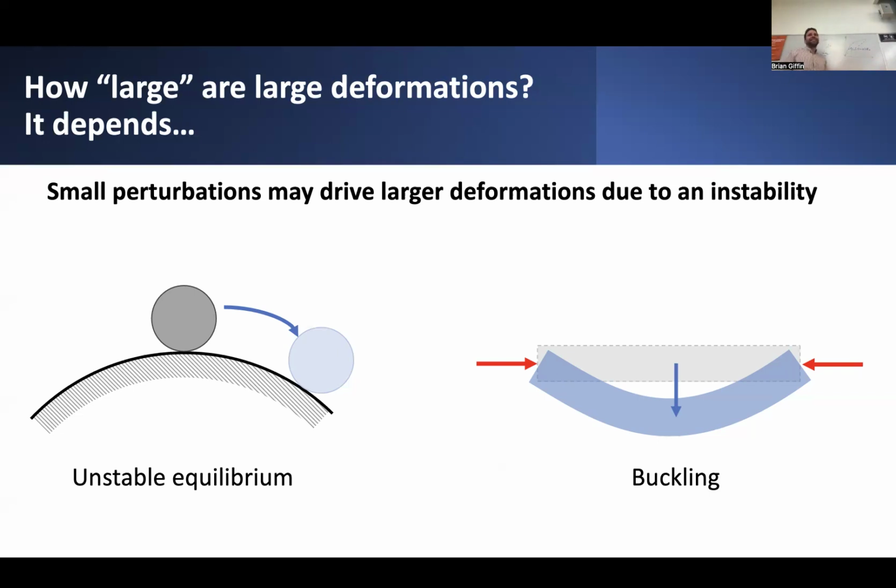So buckling, and buckling analysis, really requires that we pose equilibrium with respect to the deformed configuration of some beam or column when subjected to axial loads. So anytime you're doing some kind of stability analysis or some kind of column buckling problem or any kind of buckling analysis, you need to include geometrically nonlinear effects.